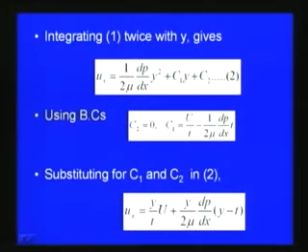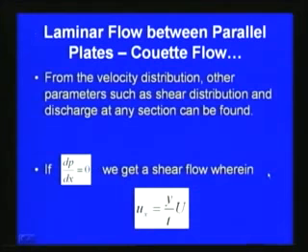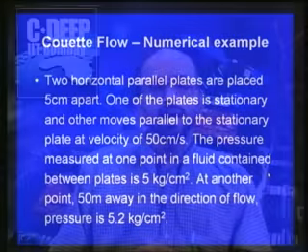From which we can just take a derivative of the velocity, and then multiply it by mu, the dynamic coefficient of viscosity, so that we can get the shear stress. And if we want to find out the flow between these two parallel plates, then we can integrate this velocity between 0 to t. The velocity into area will give the discharge passing, so we get an expression for the discharge passing between these two plates. Like that, various parameters can be found out.